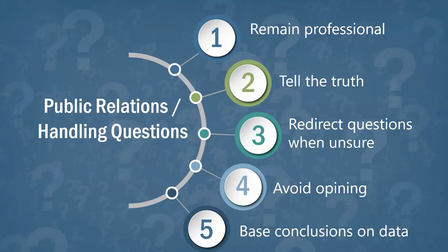So you want to tell the truth. I can't tell. There's probably some, it could be just garden variety dirt, dog hair, but it could be mold. So we're going to take a sample and we're going to determine what we have. We're not as worried about whether what's on your register is the problem as what's in the air you're actually breathing. So you want to tell the truth. You want to tell them, hey, this is where we are. This is the process at our facility to handle that.